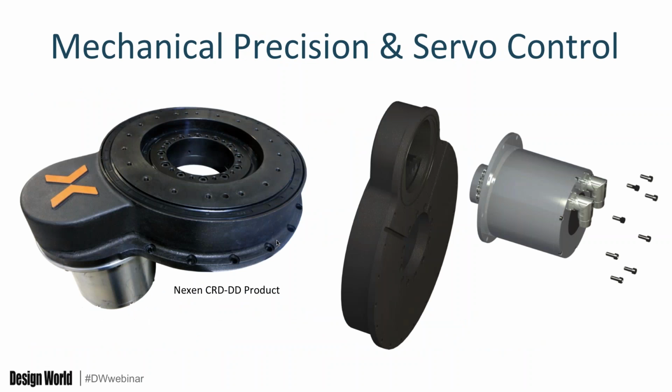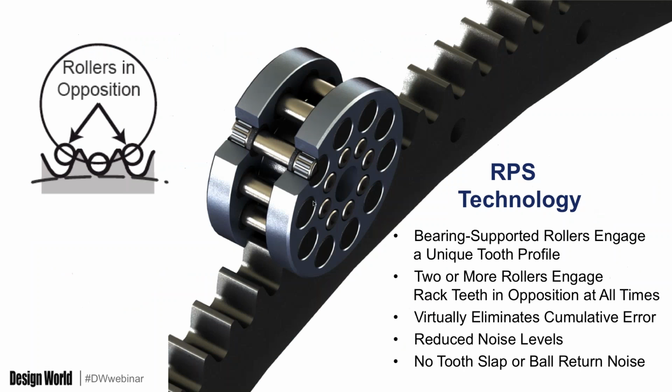So if we look at a graphical depiction, this would be typical, where you would see that with the servo motor on the right, you have a pinion, and the pinion is attached to the shaft of the servo motor, and it's going to combine with the gear inside of the housing. And this is nice because it is low maintenance. It's a sealed housing. The mechanical gearing for a wide range of different product applications. And you have the pinion, which is the roller pinion technology feature, and I'll get into that a little bit here on the next slide.